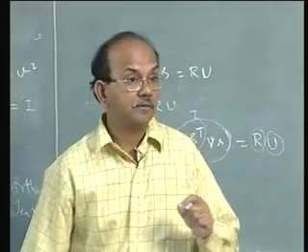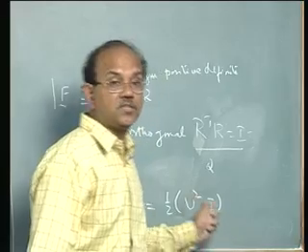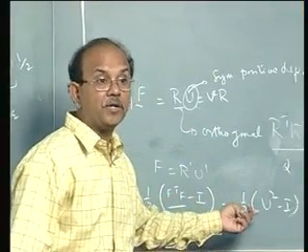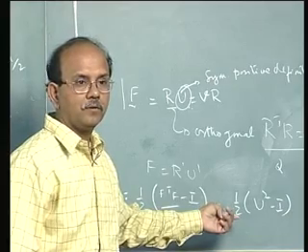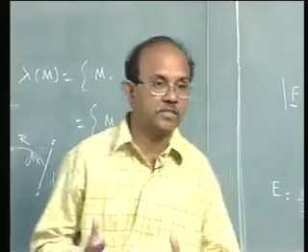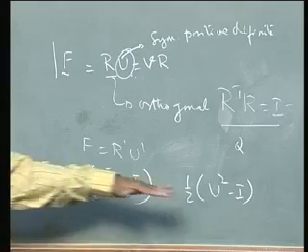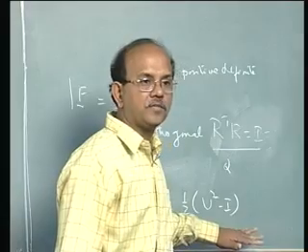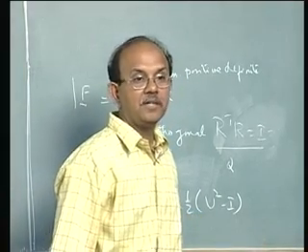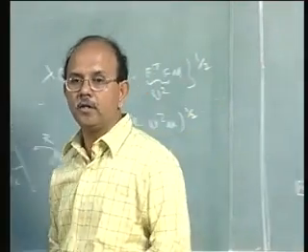Now look at this condition here, what we had written for E. We have actually been very careful in defining the strain to be one which is affected by stretch or by U alone. So this is called pure stretch because U does not contain any R in it. Hence, the strain is not affected by the rotation part of it, but is affected only by the stretch part of it.